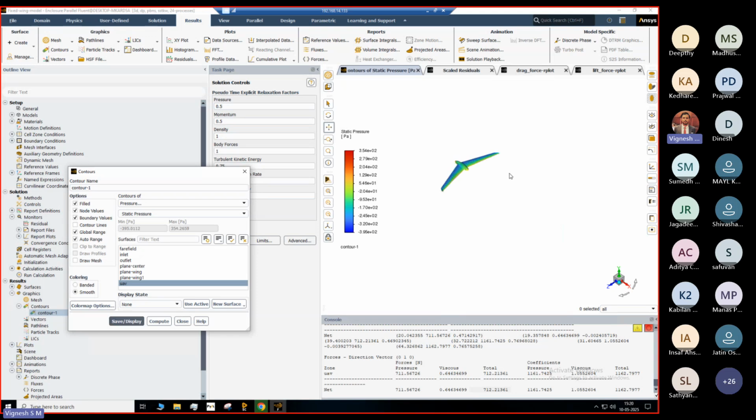So this study has been done at 0 angle of attack. Now just imagine you are doing it for a 5-degree angle of attack. The angle of attack is the angle between the free stream and the chord. Okay, but the solver doesn't know where the chord is, right? So the forces are all measured with respect to the coordinate axes.